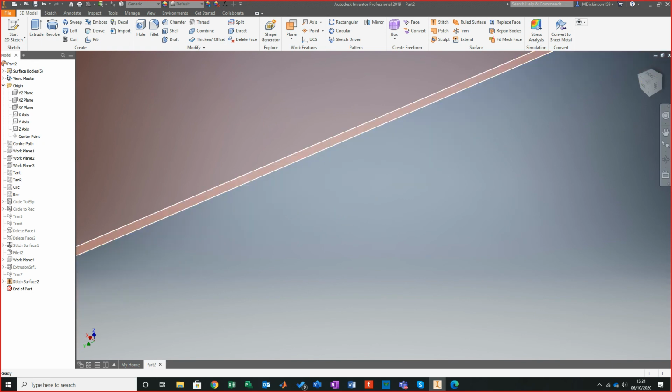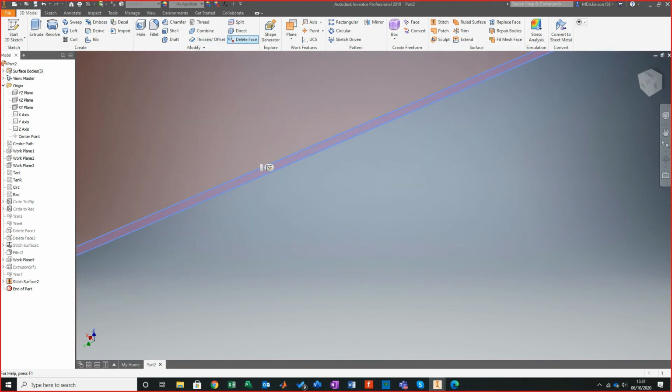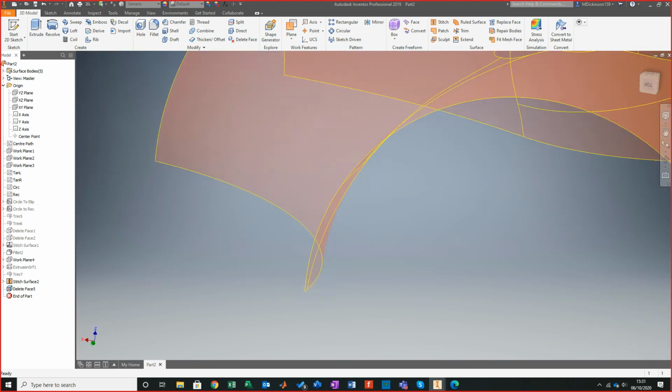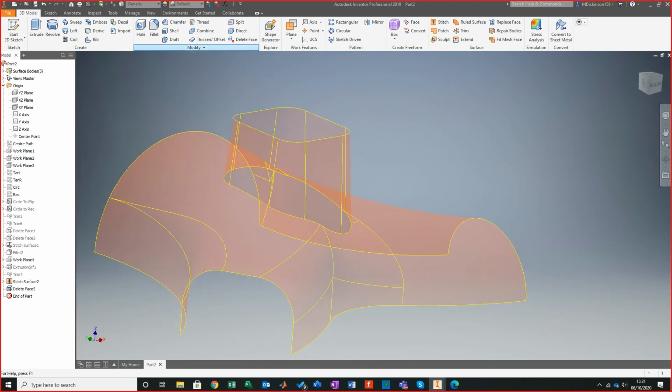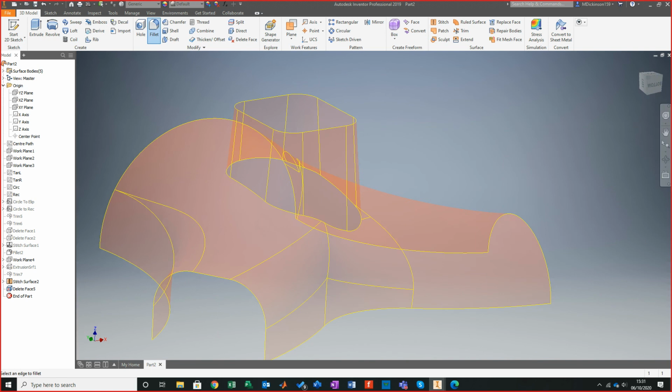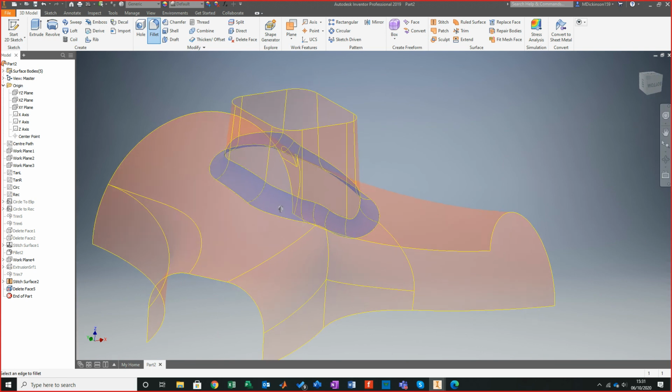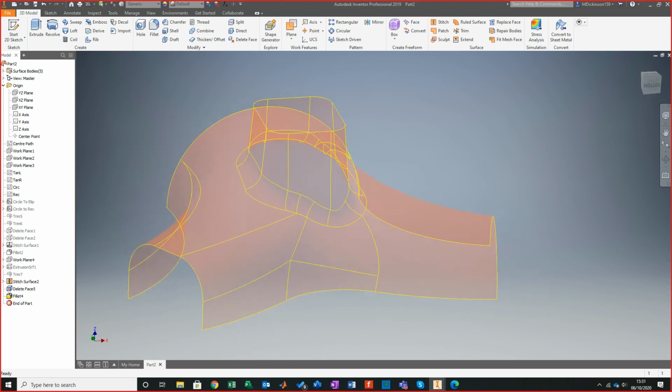And I'm just going to get rid of that one, so I'm going to delete that face. Yes, delete that face, because I know that's a problem. That shouldn't be there. It's problematic things that are there already. So then all I'll do there is add on my constant fillet. I have 12.5. And then go OK.